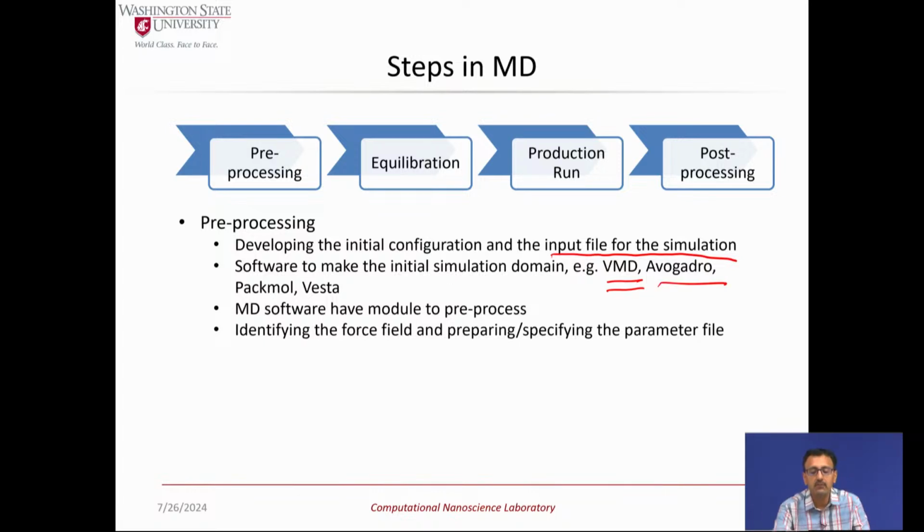There is a software, Avogadro, which is widely used in the chemistry community. It's mostly to develop chemical structures, molecules, and energy minimize their structures, relax their structure to the right states in terms of the bonds, angles, dihedrals, right? So it's pretty straightforward. Again, it gives you a periodic table, and you pick elements and construct a molecule. Once you have it, you typically use a force field such as AMBER or CHARMM, which is very diverse, not super accurate, to kind of relax the structure.